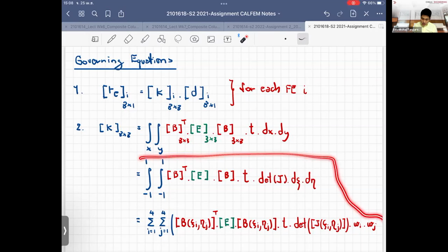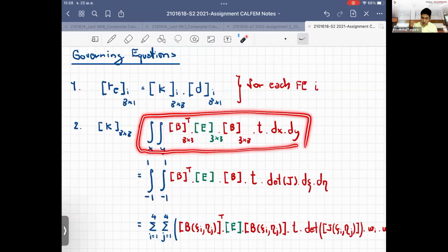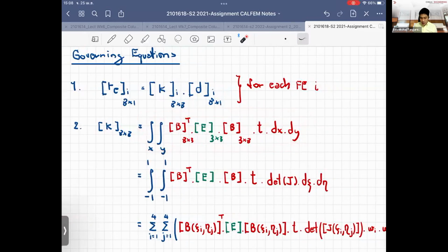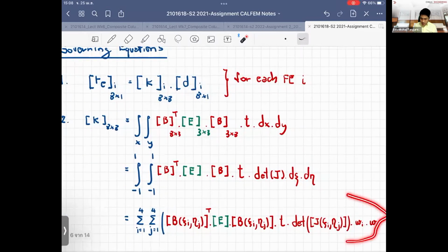The length of this depends on, okay, let me talk first. To satisfy this rule, we use the Green function. You learned that already. But following what we derived, and how we use the isoparametric properties, the isoparametric four-node or bilinear models, we want to transform the actual coordinate to what is called the natural coordinate, in terms of the xi and eta terms.